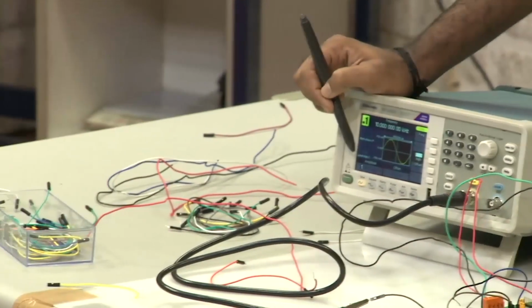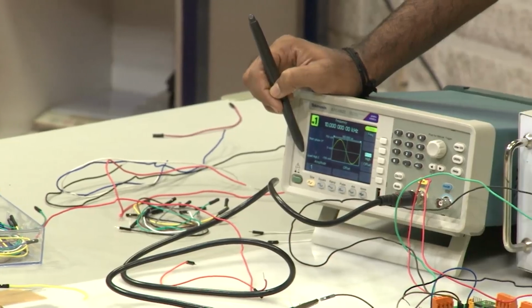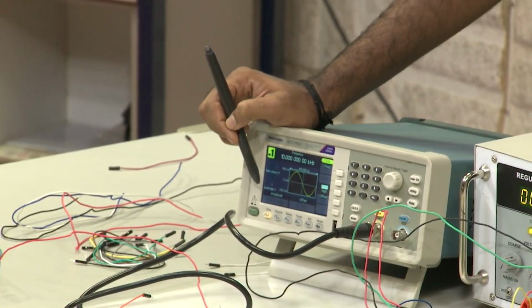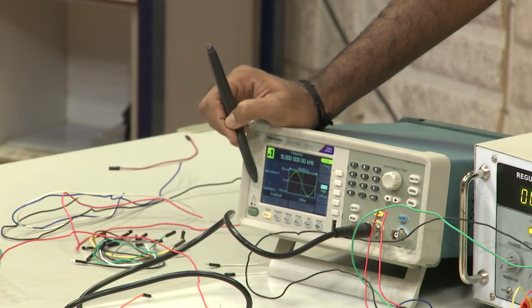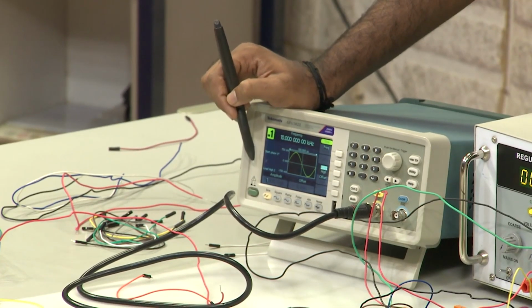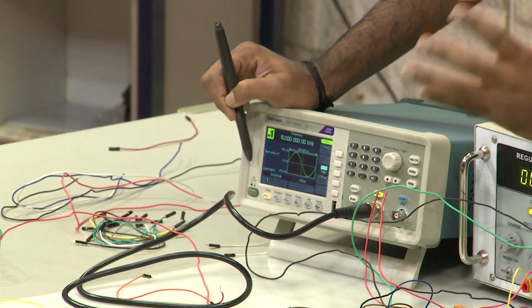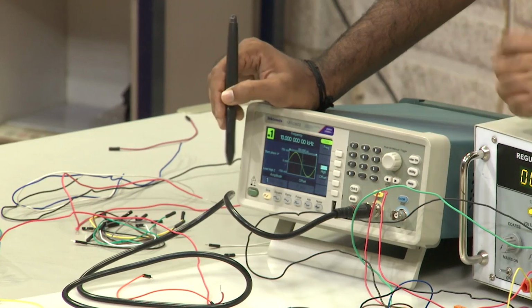So, what is the gain of our op amp? The gain of the op amp we have given is around 2.2. So, 1.5 into 2.2 will be around 3.5 volt. It is not exact, we have to multiply and see, but it will be above 3 because 1.5 into 2 is 3. So, 1.5 into 2.2, around 3.5 volt peak to peak should be your output, clear? So, this is the input.